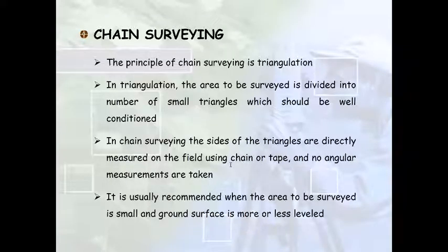So basically, when you perform survey on the land, that means that you want to create horizontal and vertical control. What that means is that you want to set out different points whose horizontal distances or angles from a reference point and whose reduced levels, that means their height above a specific point, is known.